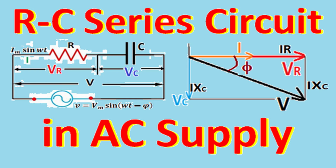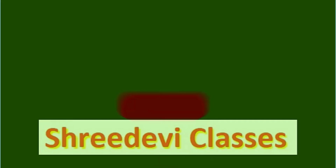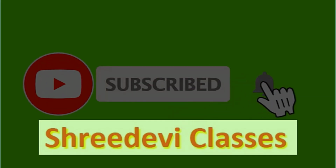We hope this simple and beautiful learning video has explained each and every study aspect of the RC series circuit in alternating current supply. Now you understand what impedance is, as the Pythagorean calculation of resistance and capacitive reactance, and by what angle current leads voltage in an RC series circuit, and that tan phi of the phase difference angle phi is given as Xc over R.